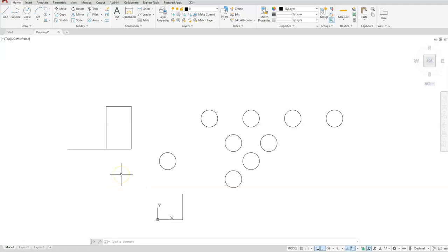Okay, so when I want to set up AutoCAD to use polar tracking method, the function key is going to be function key 10. The icon for it is going to be right next to the ortho one. Now these two can't exist together. So you can either be in ortho mode or you're going to be in polar tracking mode. And what I mean by that is that ortho only sticks to horizontal and vertical lines. This one can create in angles. So that's why you're going to see that when I select one, the other will turn off. So remember that these two cannot exist together.